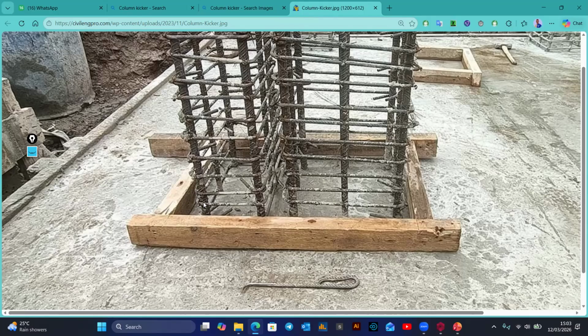Okay. So for Eurocode, the concrete cover recommends a value of 25. But in most cases, when you are on site, you find they give a value beyond 30, between 30 to 50. So when you design for a value of 30, on site this concrete cover must also be adopted as 30.